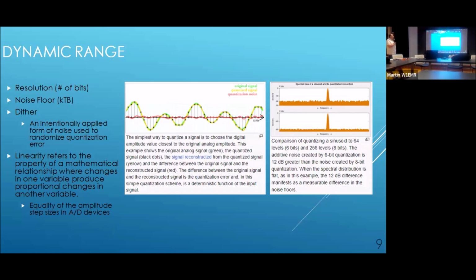Then we have dither, which is actually shaped noise that randomizes our quantization error. If we have a certain type of signal and we're feeding it into a fixed quantizer, that may produce actual distortion depending upon which side of a bias curve you're looking at. So the whole point of dithering is to avoid the bias curve. For those of us that have ICOM 7300s, we have that function built in. ICOM lets us add some dither to the signal to avoid the sampling artifacts.